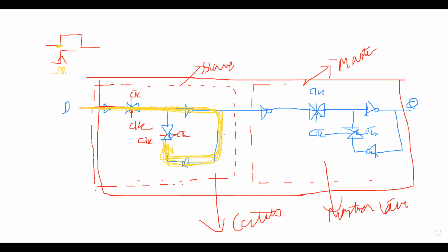How would the next data be stored? The slave latch doesn't get an idea which data has to be stored, either this data or this data. So the slave latch needs some time to store the data. That particular moment of time is our setup time. You all got it? What setup time is, and why we need setup time?